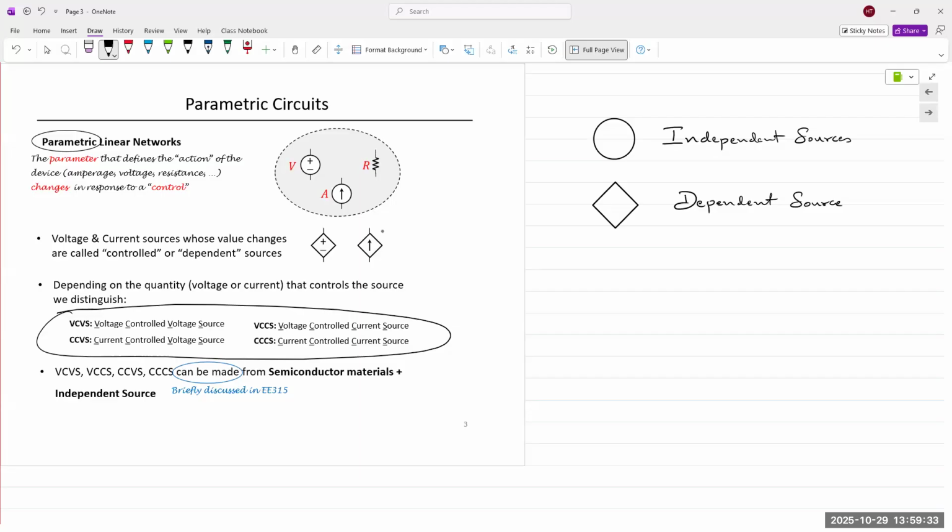In that example, I had 9 resistors and I had 9 volts connected to those 9 resistors in series. So every resistor had 1 volt across it, right? So every output across every resistor can be considered as a dependent voltage source. They're all supplying a certain voltage, but that output depends on the input. If my input goes from 9 to 18, what happens to the output of the resistors? It's going to double, right?